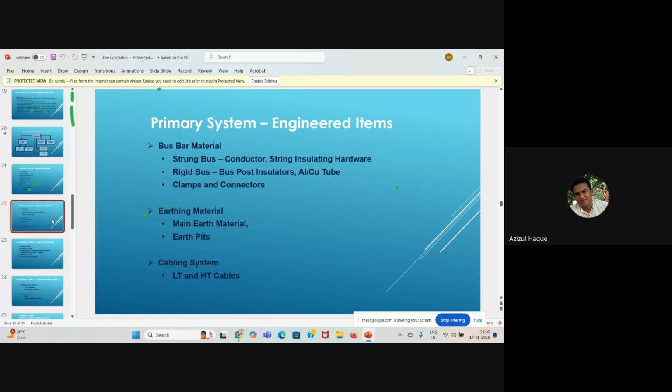We have to break at places and have some gap in between, because with temperature variation, season variation, there will be some expansion and contraction of the tube. So we have to design our connectors to accommodate that expansion and contraction of the buses also.